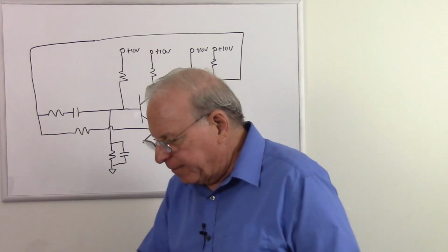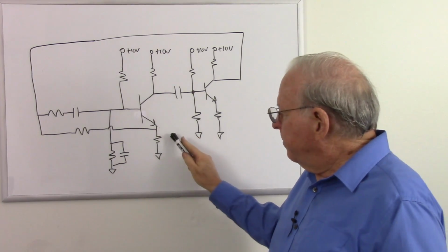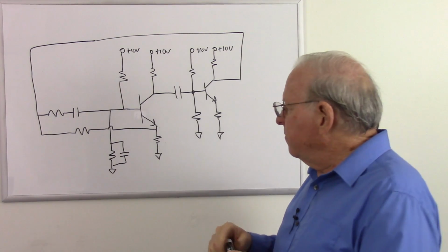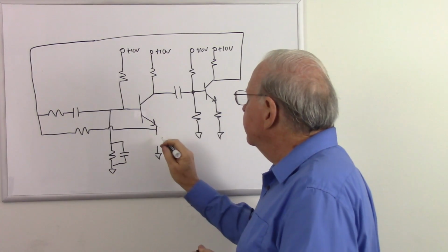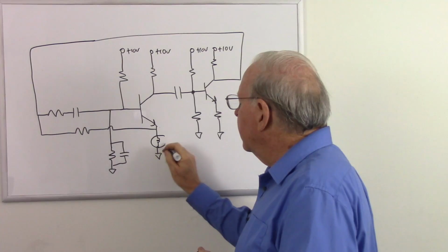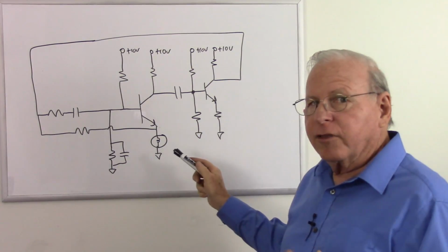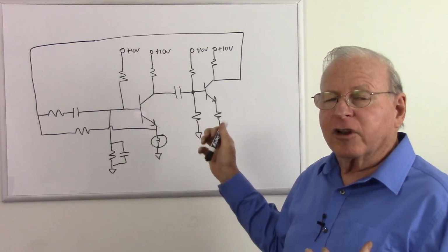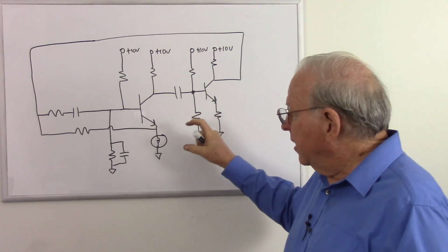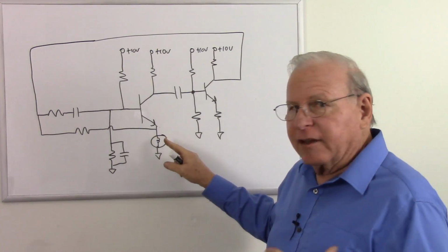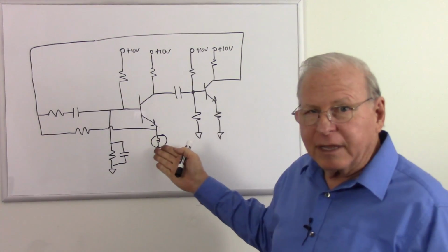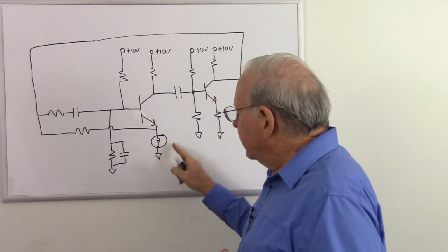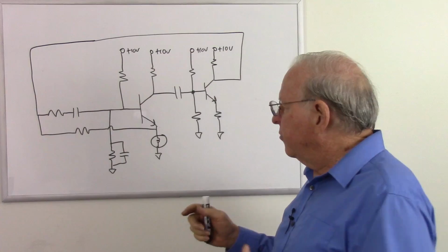And might as well mention at this point, it's still very hard to control. So typically a Wien-bridge oscillator will have something here to help control that negative feedback. Early Wien-bridge oscillators put a light bulb here. So what does that do? As we increase the current through the light bulb, its resistance increases. So it gives us more negative feedback. As we reduce the current through the light bulb, its resistance goes down, so we get less negative feedback. Now, it doesn't necessarily have to be enough power to make the light bulb light up, but just enough to warm it up. But that's also going to have a little bit of a time lag, so it won't work very well at high frequencies.